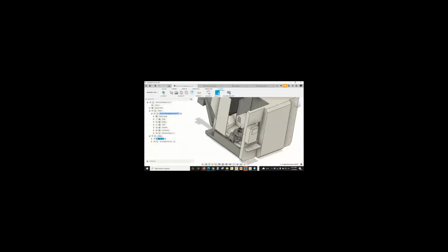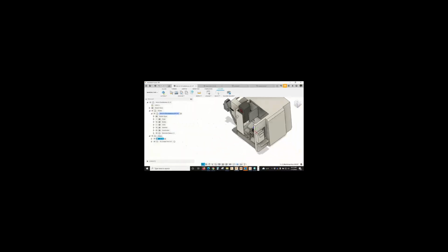So we just have a lot of control over where we want to put this fixture. And just like the movement tool when you're 3D modeling, or the movement and positioning tool that's built into Fusion, I can grab these wheels and move this anywhere I want to move it. Okay? And we can also put in some hard values in here if we actually know where this fixture sits on our machine. Okay. Scroll back out.